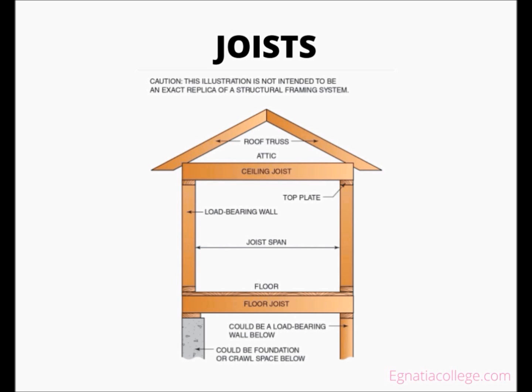The joists that separate different levels of a house are floor joists, and ceiling joists are the structural boards of the highest ceiling in a house. The size of a joist depends on the design intent and the structural load of a particular area. Two common sizes are 2x8 and 2x10. But a 2x12 size is used for larger buildings or for greater span requirements.